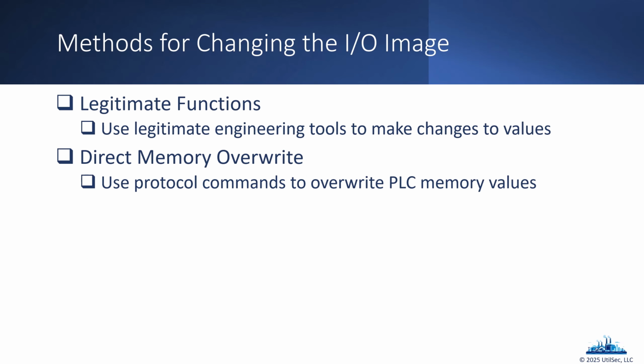Now, how do we make changes to the memory running in the PLC? I think we've already done this a couple of times through class. You can use the software that comes from the vendor that allows us to interact with those systems. Or again, we can connect over one of those unauthenticated OT protocols like Modbus to make those changes. No username, no password. Usually when you use the legitimate software, there's at least a password involved.